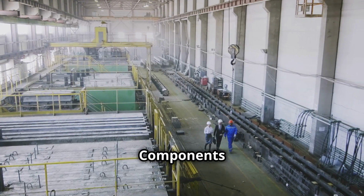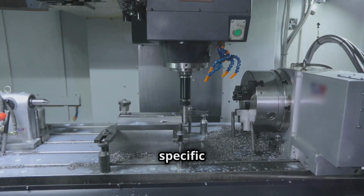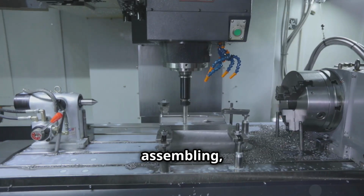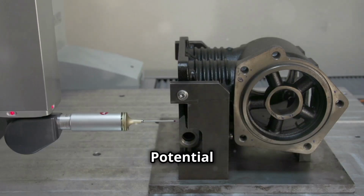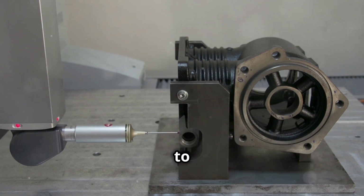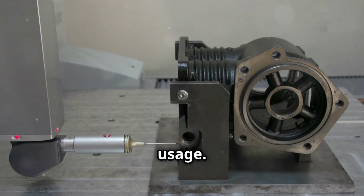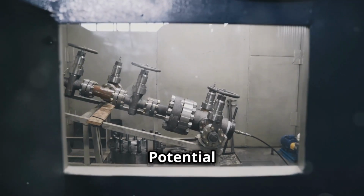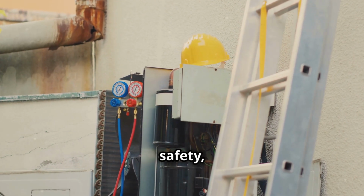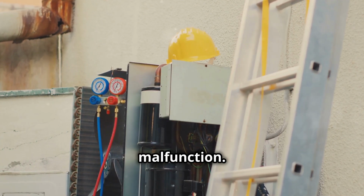Key components of PFMEA. First, process steps. These are the specific actions taken during production, such as machining, assembling, or painting. Next, potential failure modes. These are the ways in which a process could fail to meet its intended function, like poor fit or wrong material usage. Then, potential effects of failure. This is the impact of failure on product performance, safety, or quality. For example, component failure or system malfunction.